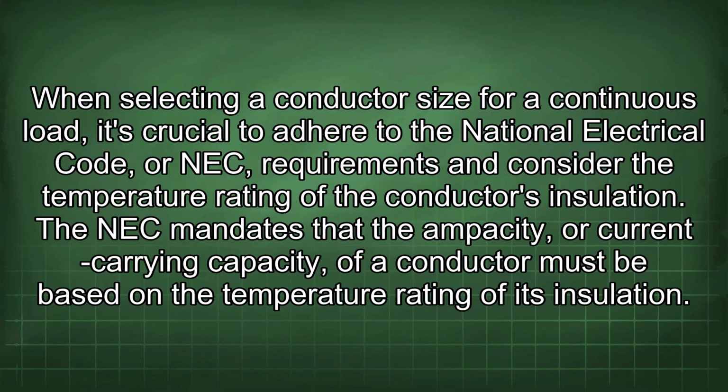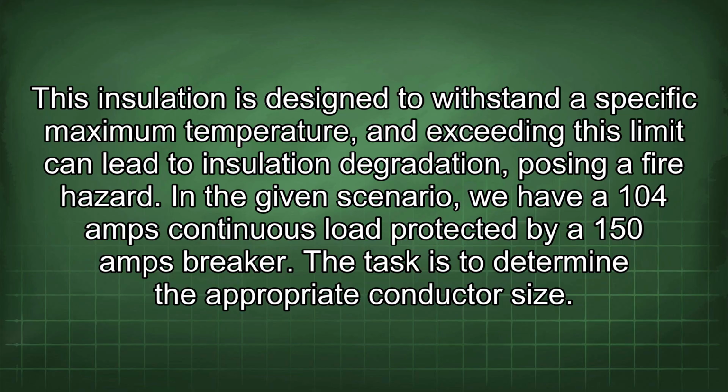When selecting a conductor size for a continuous load, it's crucial to adhere to the National Electrical Code, or NEC, requirements and consider the temperature rating of the conductor's insulation. The NEC mandates that the ampacity, or current carrying capacity, of a conductor must be based on the temperature rating of its insulation. This insulation is designed to withstand a specific maximum temperature, and exceeding this limit can lead to insulation degradation, posing a fire hazard.